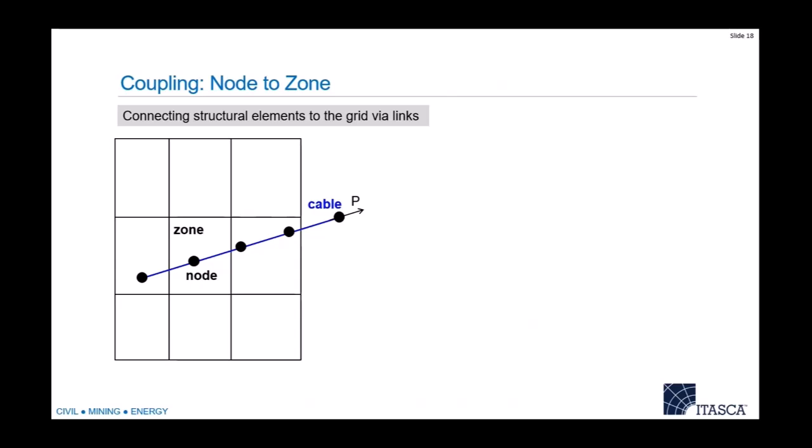They need a way to connect the pile to the concrete sheet, and you can specify how that interaction will take place. It can be rigid. A lot of times that's bad because high stresses will develop at that rigid contact or connection. Or you can define it to be deformable and give it your own stiffness and other properties.